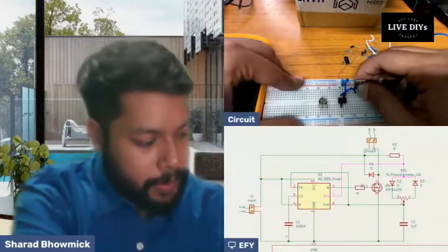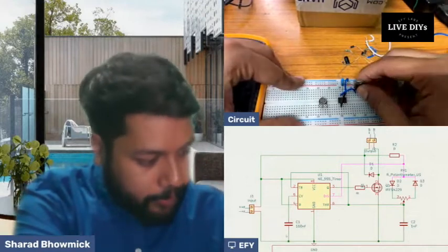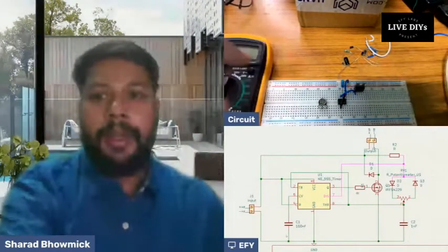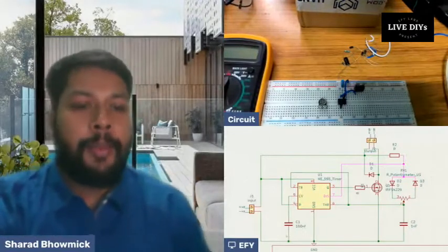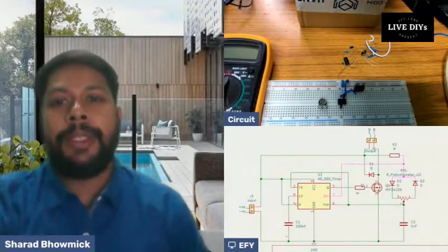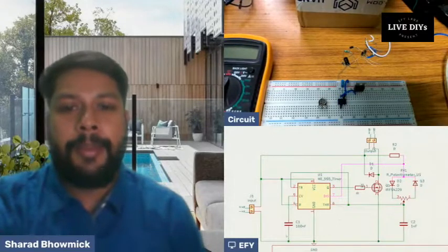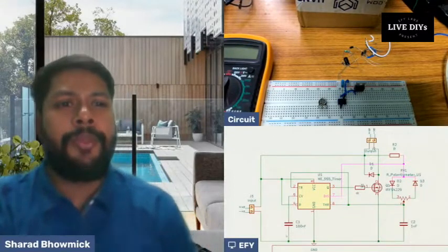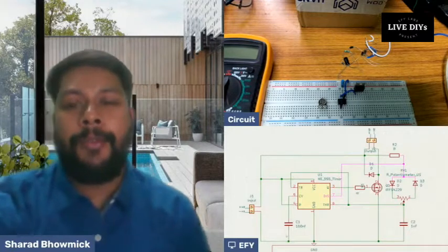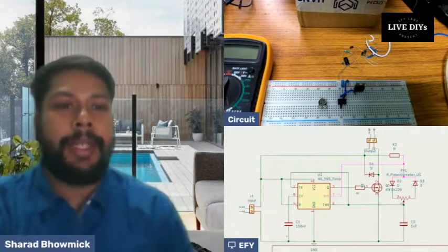Now we change it because we'll need it. Now fourth and eighth are connected to our positive terminal. We have to understand that pin number 8 is VCC, whereas the fourth is the reset pin. We don't need to use the fourth pin here, but we can, if we wanted to switch off the circuit